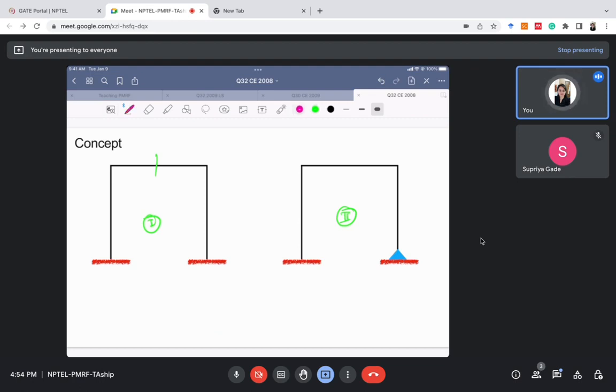Now the formula says degree of static indeterminacy is 3c minus r dash. So ds will be, how many cuts have we made here? Number of cuts is one, only one cut we have made, minus number of restraints to make each joint rigid. For this structure, every joint is already rigid. This joint is rigid, right?